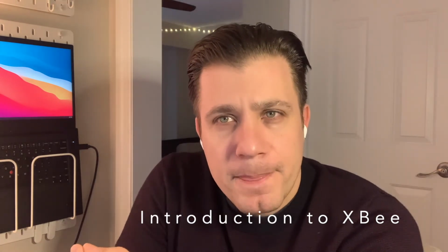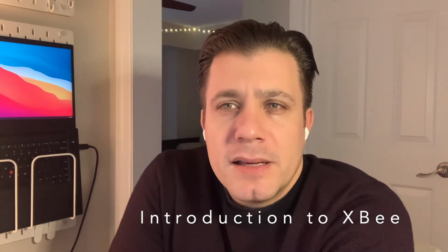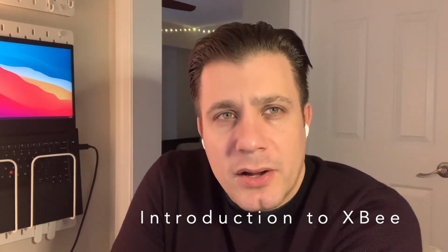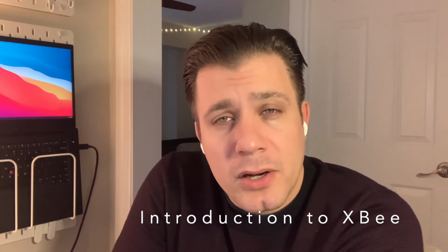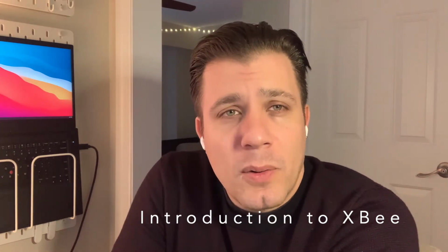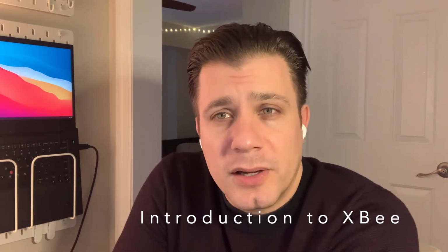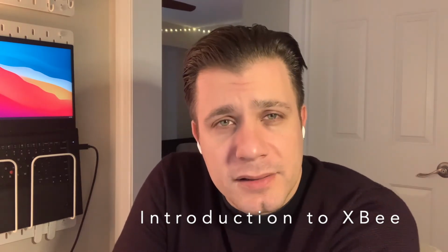Now, XBee. So XBee and ZigBee are not the same, and what's the difference? ZigBee, like I said just a second ago, is a communication protocol. XBee is a hardware module and form factor. It's a line of products that employ a version of the ZigBee communication protocol. They're manufactured by Digi, but there are compatible devices available.